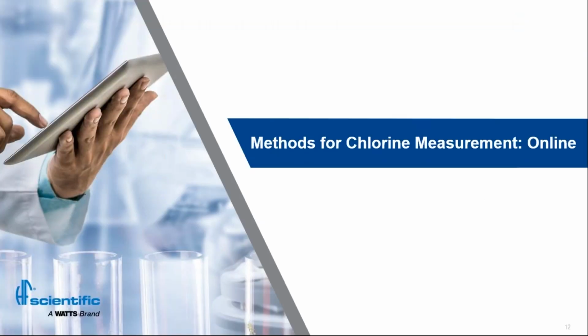And now we're going to move on to discuss the methods for chlorine measurement online. Many of the technologies are going to be similar, but they have to be applied differently to make the analyzer work well online. In this section, we're going to cover both batch and continuous operation analyzers. But the time required for the batch reaction for a chlorine analysis is very short, so this is not usually a deciding factor in the determination for the best analyzer for a municipal water system.